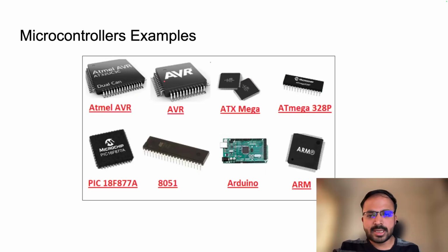Now, microcontroller examples. This course will deal basically with Arduino; our focus will be on Arduino. That is a very good example of a microcontroller, because you will have the microprocessor, but your other modules are integrated on the same board, on the same circuit. Timer modules, IO ports, and counter modules all come in the same chip. So it's an example of a microcontroller.